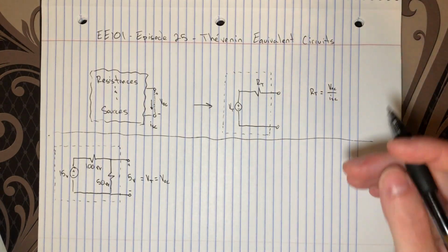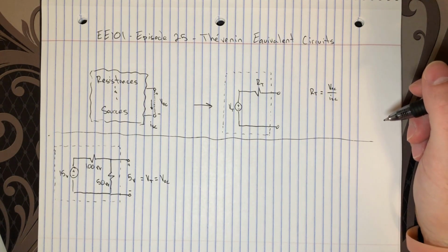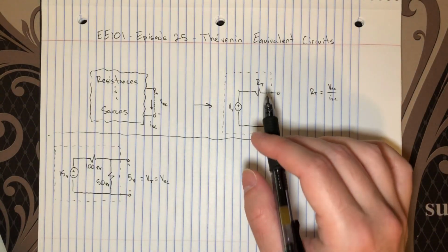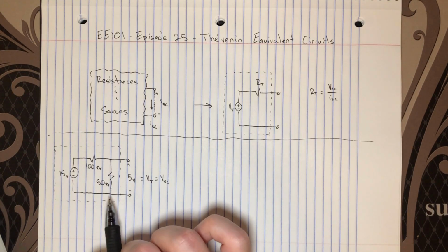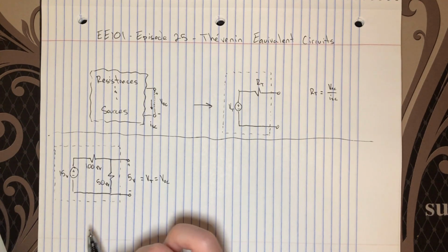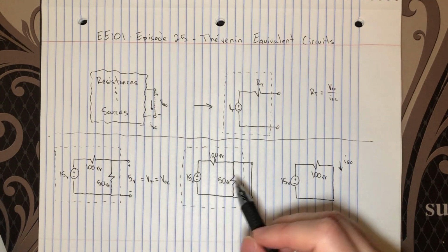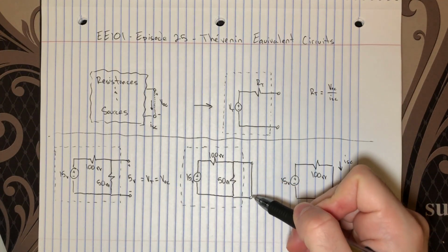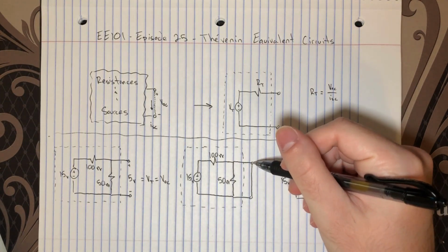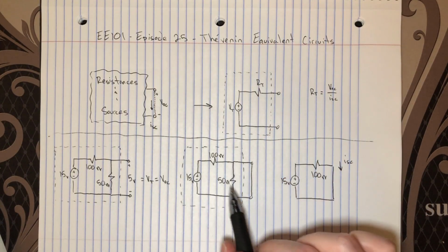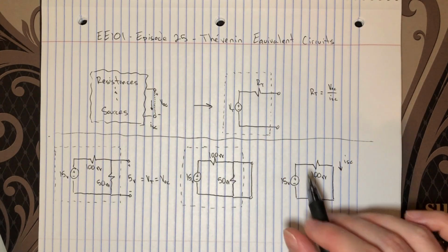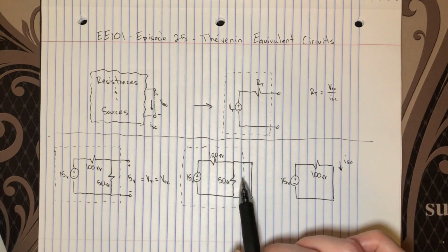Look at us go. So now, how do we get the R Thévenin? Well, like I said, we're going to have to calculate the short circuit current. Okay, so I've just redrawn the circuit, but with the short applied across the nodes. So we've shorted the terminals that we want to look between. And then I even drew one more little circuit just so you see the equivalence and don't get distracted here.